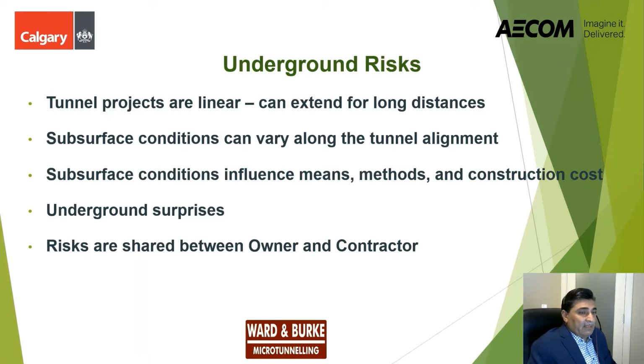And if there is variability in ground condition, then that variability influences means, methods, and construction cost. And remember, there are underground surprises. We should expect those unforeseen conditions. And so that is a big risk. And that risk is shared between owner and contractor. So if there is change in ground condition, someone has to take the risk. And then risk is shared between owner and contractor based on what? Based on the geotechnical baseline report that we'll discuss after this slide.